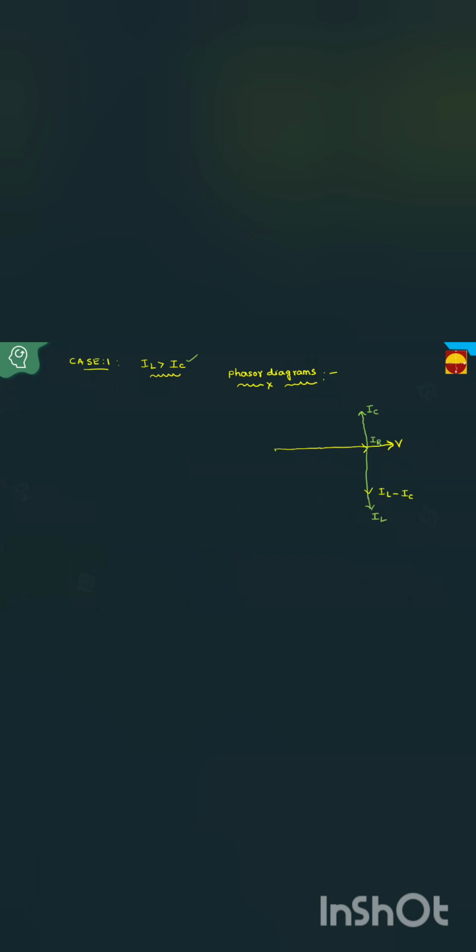The same concept I discussed even in the series circuits. This is the resultant, this resultant is I. This is the theta. Clear? Then take any angle: the angle between IR and IC, between IR and IL, between IR and IL minus IC, between IC and IL. This is 90 degrees, this is also 90 degrees, and this total is 180 degrees.